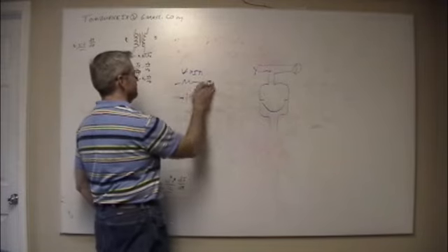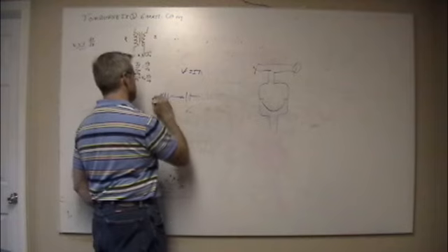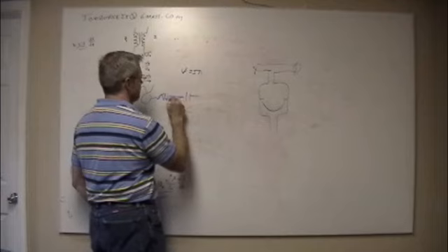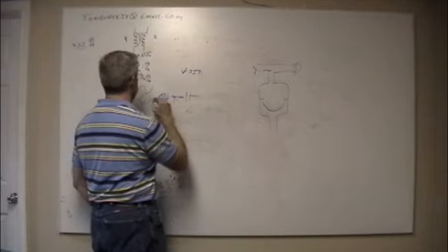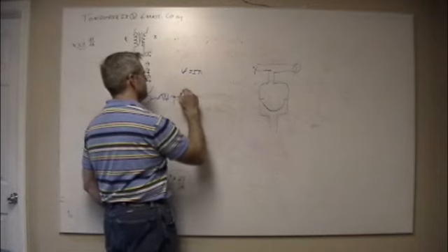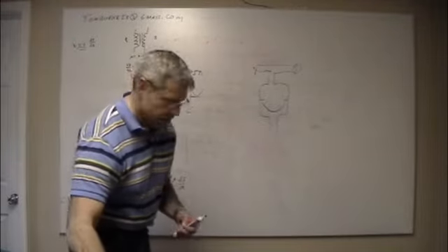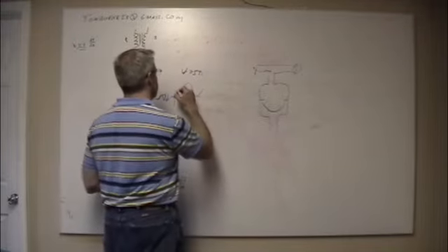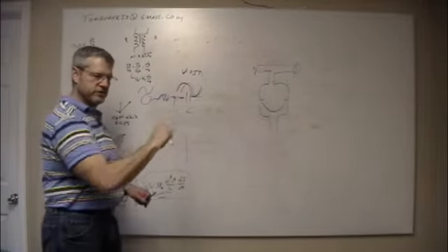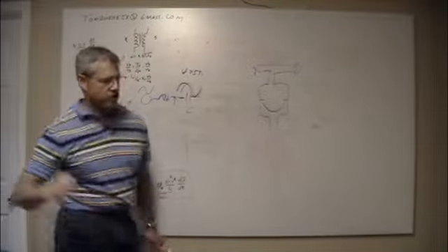So if I do this, I've got a voltage source here, and he's putting out a sine wave. And if I measure voltage and current, if I measure this, it's I, and this is voltage here, I'll see current here in time. Current leads voltage. Because as soon as that voltage starts coming up, it's at a high frequency, this thing looks like a dead short, lets the current flow through.